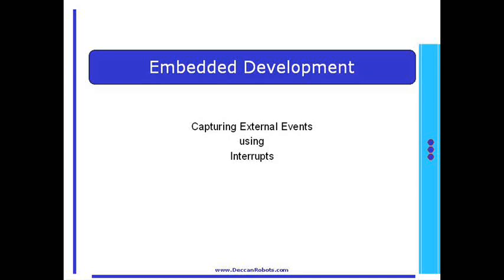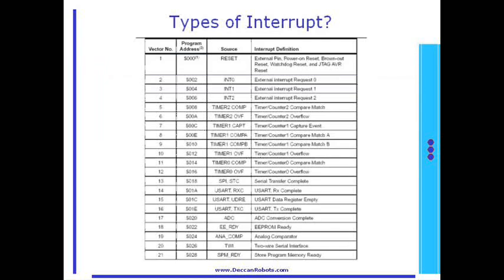An interrupt is when the processor immediately stops what it is doing and heads on over to some other code segment when something happens. This something can be triggered internally or externally, such as when a key is pressed, a timer counts down to 0, the analog to digital converter has a result for you, etc. Mega32 has 21 types of interrupts. The number of interrupts and their types will change from one microcontroller to another.